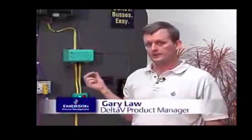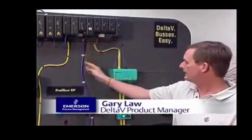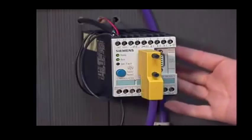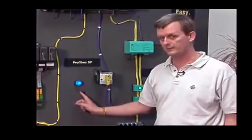Now, the components of a Delta V Profibus solution. We have the Profibus DP interface card with one port. In this case, we have it connected to a Siemens Simocode motor starter. The Simocode is one of the more popular devices on Profibus. In this case, the Simocode is wired up to a light bulb to simulate a motor. We have a switch to control the current feedback.